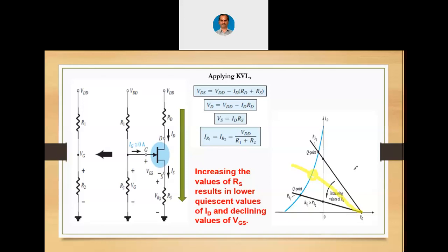But in the FET, we don't use the load line as such, because there is no beta here and we cannot actually use the load line in that sense. We will have to plot the transfer curve. Using the transfer curve, again we can set the Q point. That is the idea here. Anyhow, we have to make use of the transfer curve when we use graphical analysis. So there is no point in drawing the load line when we have a transfer curve itself.